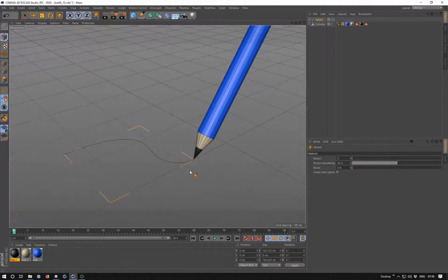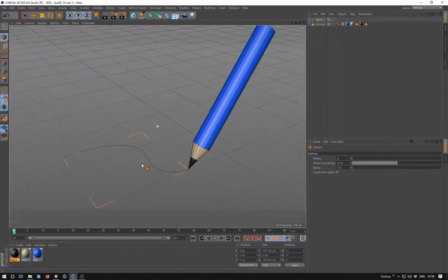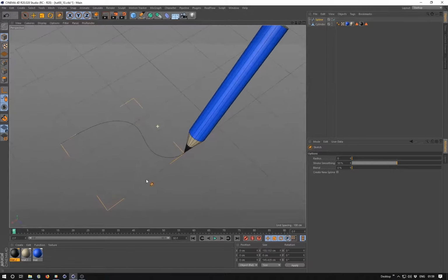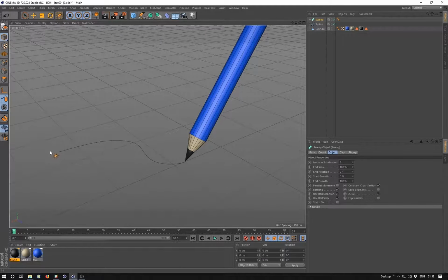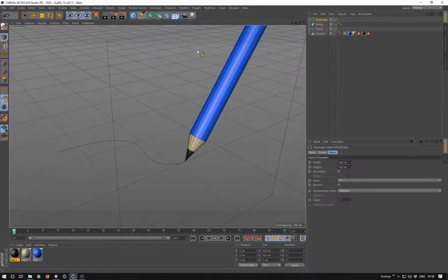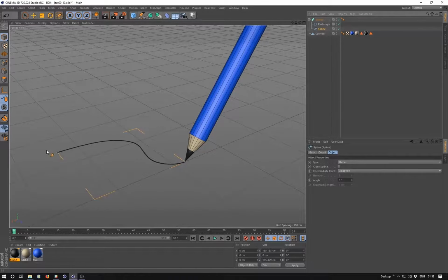The spline is ready. Now we just need to create a geometry based on it, because it won't render itself. We can do so with the help of the Sweep operator, which builds 3D objects by extruding a section along the path. We have the path, now we need a section. Let's create a rectangle and make it a bit smaller. Drag it under the sweep. Right behind it, we have a path; we have to place the section on it.